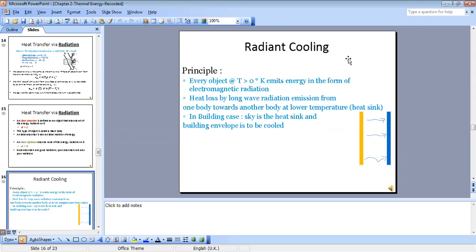So for example, during the night, the external environment is at low temperature. So we can evacuate heat from the internal space through the external surfaces of our building, in general mainly the roof, okay? So the roof can radiate towards the sky, which will be at lower temperature. And by radiation, we will cool our home.